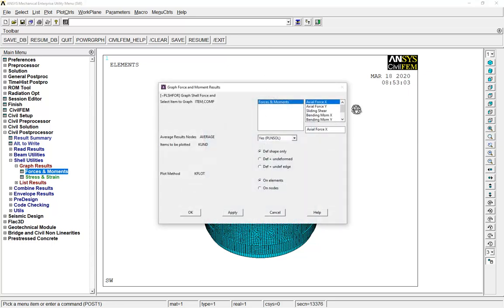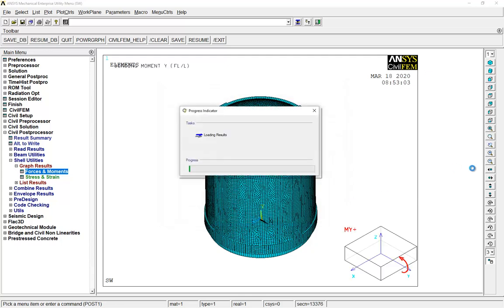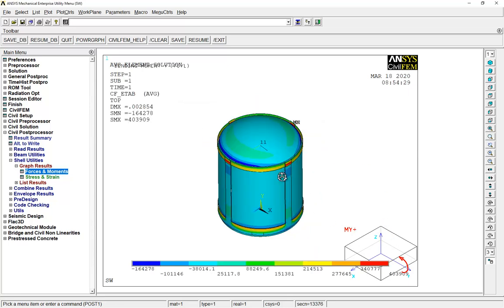For example, I'm going to plot a bending moment about Z axis. Here you can see CivilFEM also adds a symbol, just explaining what we are plotting. We also have the design criterion: positive bending moment around y-axis is this, which has compression on the positive part of the z-axis. Well, here you can see the bending moments we have due to self-weight.